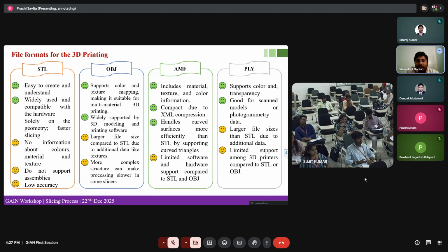While less common, this is very uncommon in general prototyping, but it is a standard for research and scanning-heavy workflows. So where you are using scanning, this file format is used more. PLY's strength lies in its flexibility, because 3D scanning often introduces sensor noise, and PLY supports the storage of data confidence values directly within the vertex properties. This allows researchers to distinguish between high precision data and interpolated points.